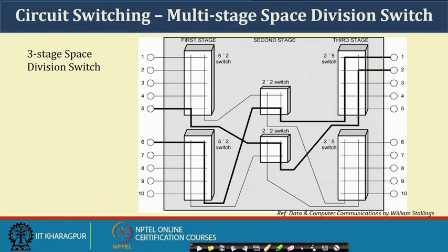So we can have multi-stage switching and still establish connectivity. But then we have to look at whether it becomes a blocking or non-blocking architecture, how many can simultaneously talk to each other, and so on. Those considerations come into play, so there is a need for overall planning when we go for these switching strategies.